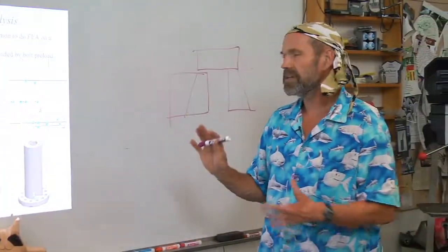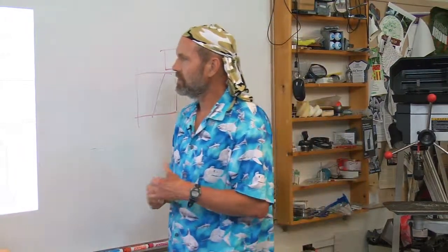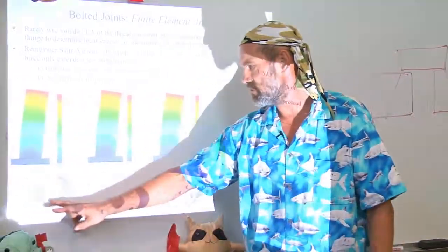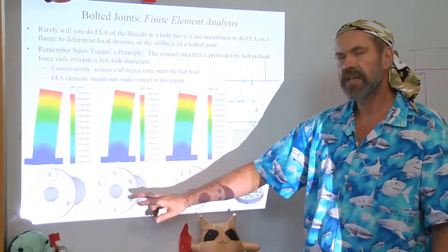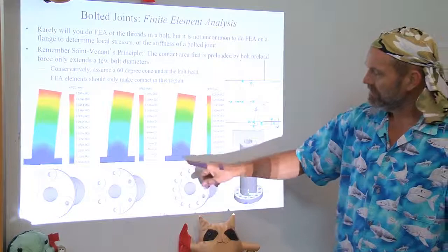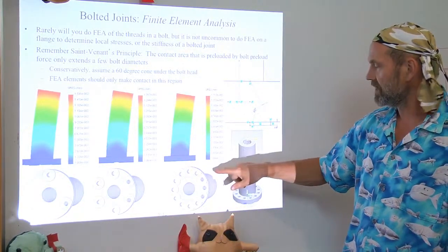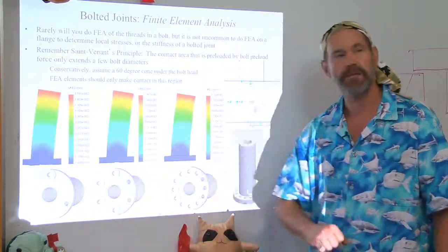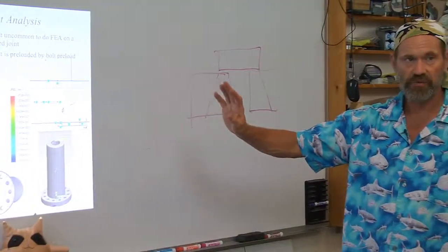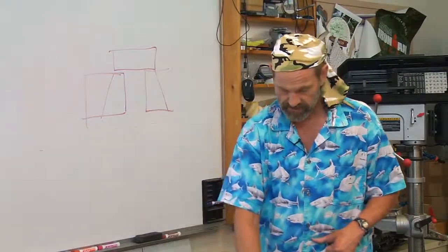Is that a lot? It depends upon what your machine was intended to do. It seems to me that the biggest gain goes from 3 bolts to 6. There's not that much added gain when you go from 6 to 12. The reason you'd use 12 is if you had a sealing function also. If you didn't have a sealing function, the 6 bolts should be plenty. But again, you can run the numbers and determine exactly whether what you're getting is what you need or not.